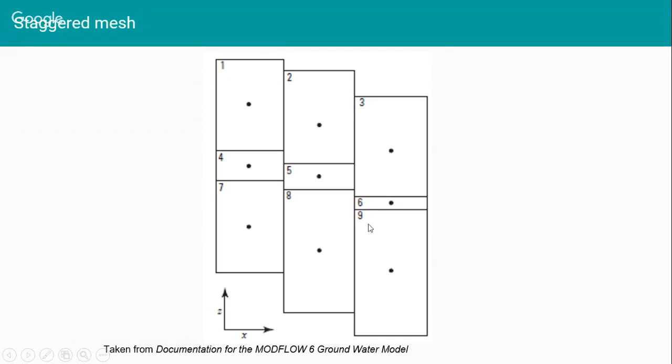So this mesh, by not needing layers, allows the user to control the number of elements in the mesh in all directions, regardless how complex the numerical model becomes. So you can control the size of the elements, and therefore you can do local refinements in places of interest without increasing the number of elements to a large extent. Really, this is a very, very wonderful feature of MODFLOW 6.